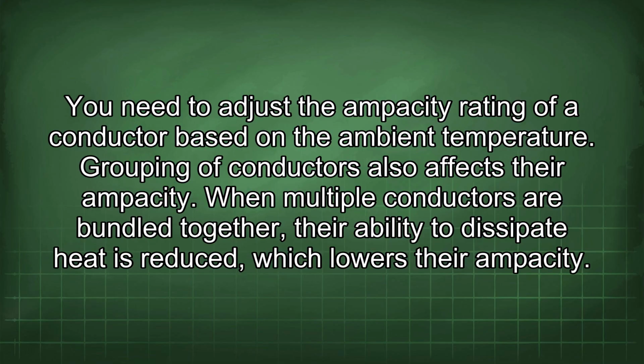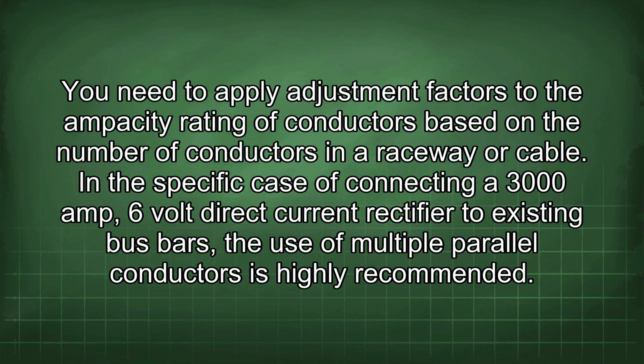Grouping of conductors also affects their ampacity. When multiple conductors are bundled together, their ability to dissipate heat is reduced, which lowers their ampacity. You need to apply adjustment factors to the ampacity rating of conductors based on the number of conductors in a raceway or cable. In the specific case of connecting a 3000 amp 6-volt direct current rectifier to existing bus bars,